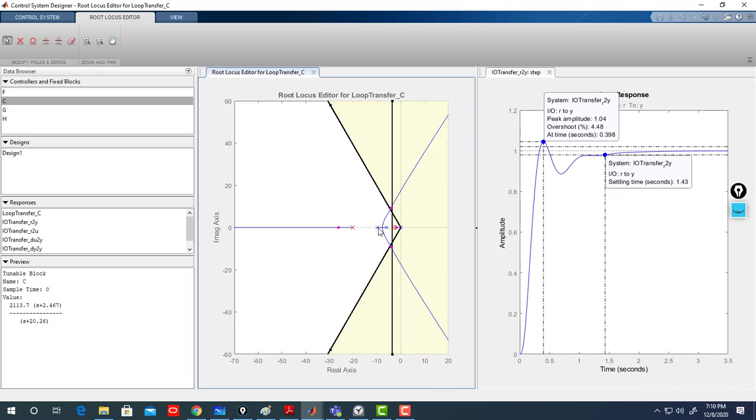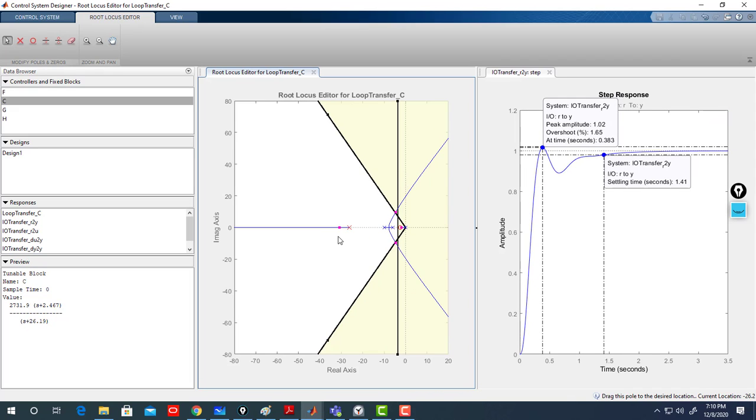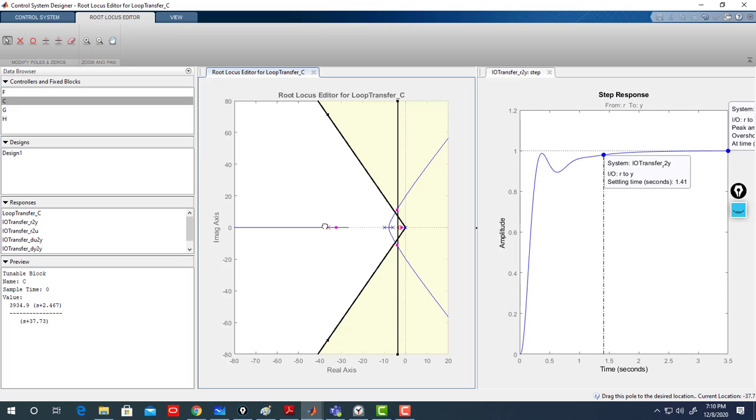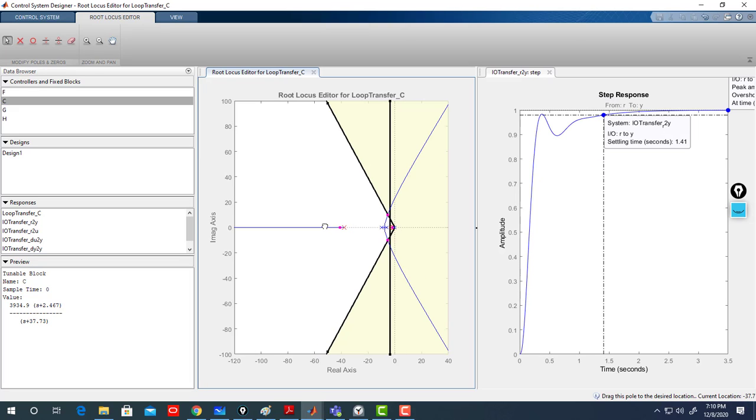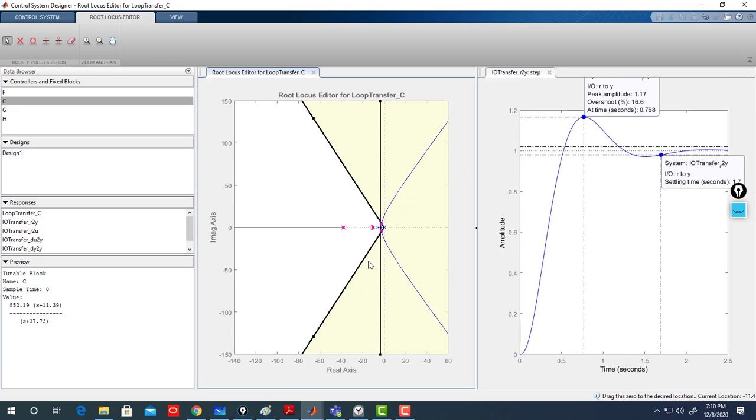Right, so maybe it seems like this zero location really doesn't help on providing overshoot, so it really excites your actuator. You need to put the zero this way. This compensator will provide a high control signal and therefore less overshoot. So then maybe it's a good way to reorient your zero. See, I reoriented my zero.